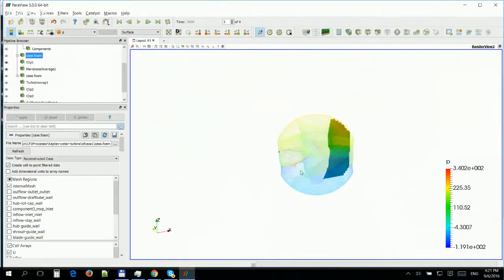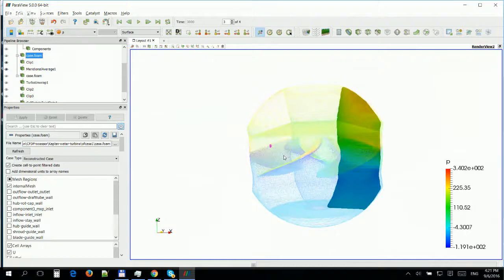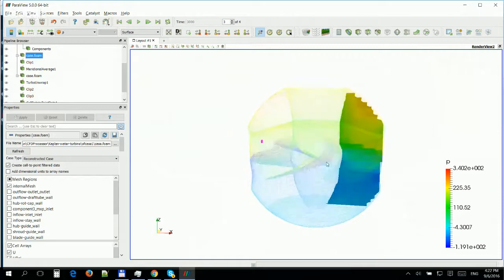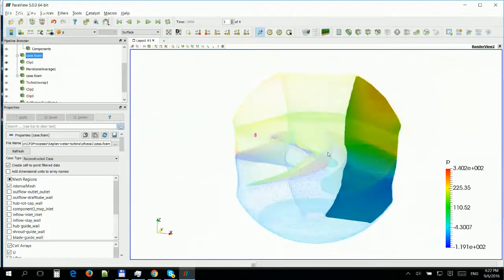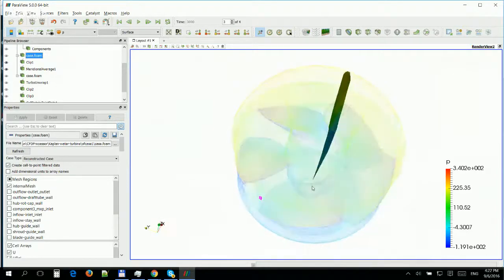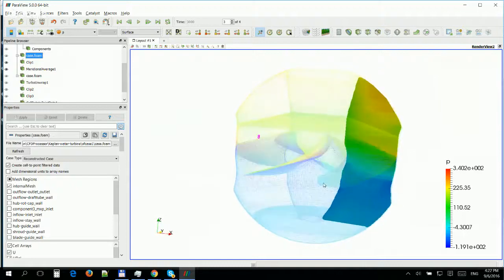And we have implemented a couple of functions together in a special set of plugins, which is called Turbo Blade Post. Turbo Blade Post is included in Turbomachinery CFD, and one of its very important functions is called meridional average. You can average any quantity in a meridian of your rotor.